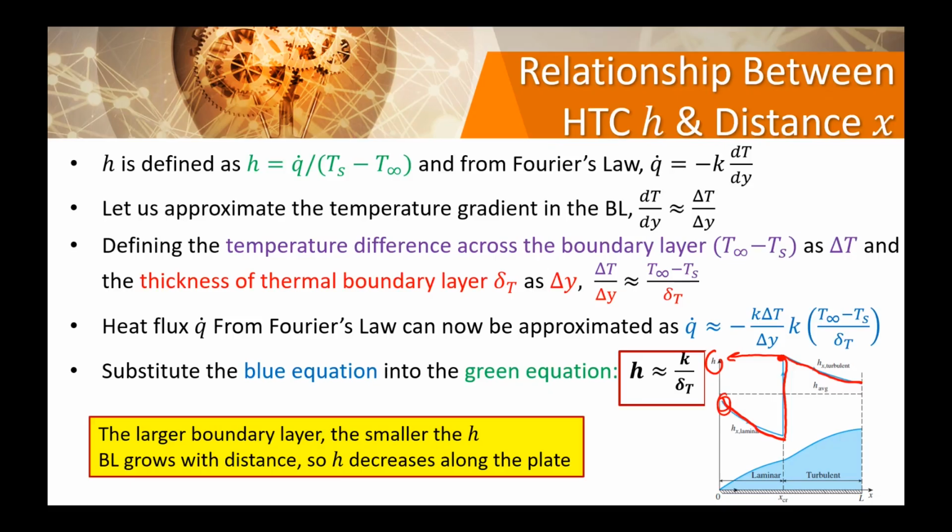So that's why in heat transfer applications, we need turbulence. We always prefer the turbulent regime for heat transfer. But for reducing drag, the drag of a car, the drag of an aeroplane, we want the laminar regime. We want the flow to be smooth and streamlined. We don't want it to be chaotic with induced wake behind the geometry.